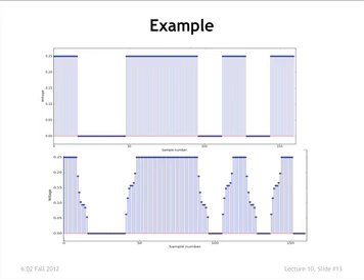All right, we've seen this visually too. I did an example last time where what went in was that square wave, and what came out after we'd done the demodulation and the filtering was a response that sort of had the features of what went in, but it was a little distorted. So you can see that what we're looking at here, for instance, is the character of the step response, because right now the input and the output are at rest. Okay, you've forgotten about what happened before, and now the input jumps up. Well, the output doesn't jump up all the way immediately.